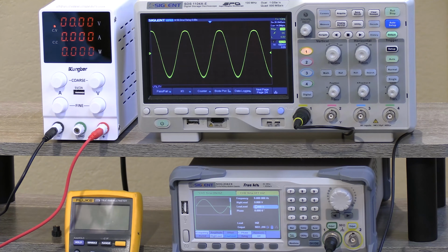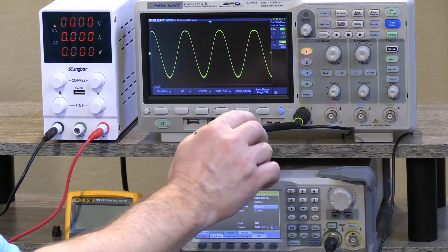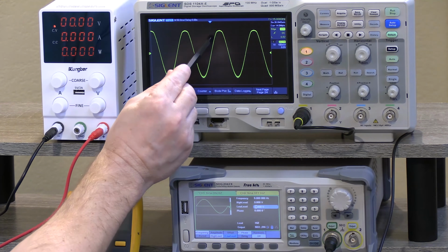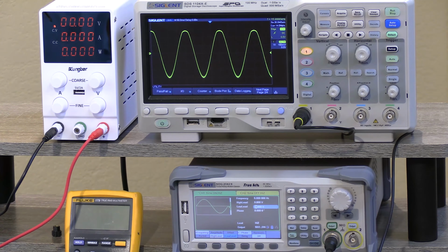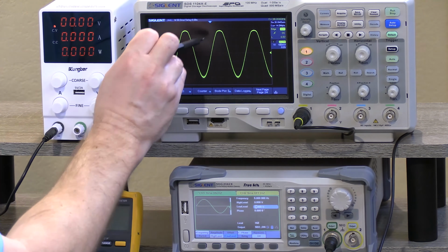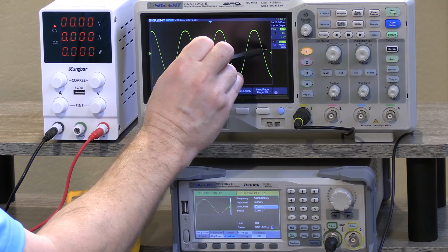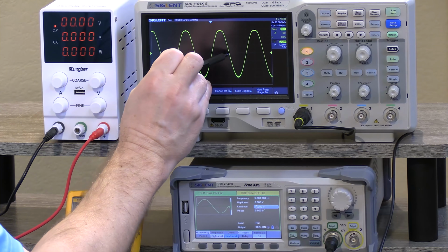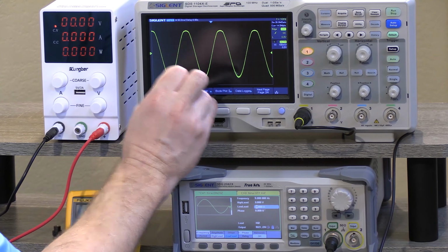What's happening here is that basically inside of this conductor, there are actually two wires, right? You can see the two wires are connected over here. And what it means is that when I'm going up on the positive side, then the red wire here is going higher and higher and higher in voltage. That means the current is coming into the circuit through the red wire and going through there. But eventually, the voltage drops back down to zero. Remember, this tick here is the zero axis, so it goes back down to 0 volts, but then it switches to negative voltage.